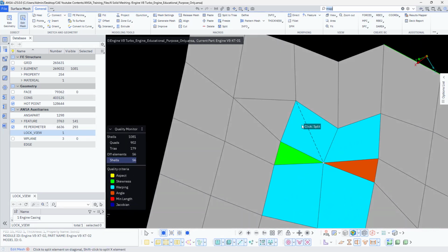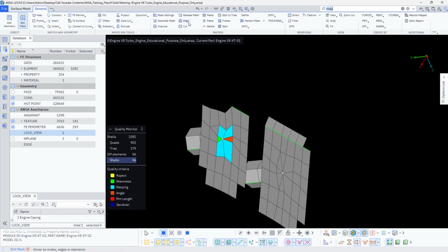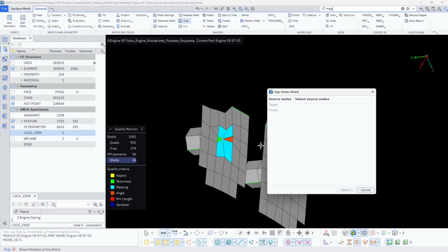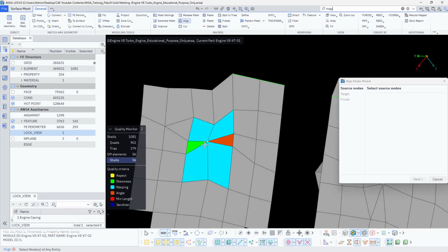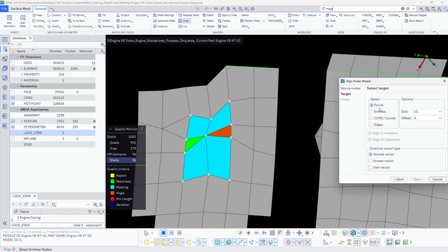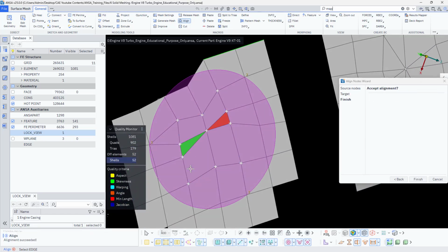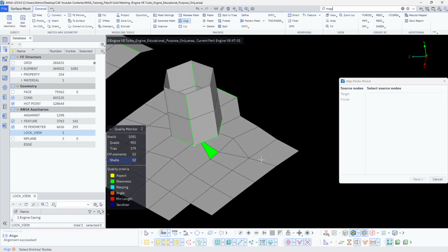Now you should align this with this surface. For that, you can go ahead with the align tool. So we have the shortcut also. Alt A is the align. So you can select the elements. So you can even select with the entities also like this. Okay. So these are the regions which I need to align. So middle click. So it will ask you for the normal to vector and points. So I'd like to define the regions. Like if you define 3 points, it will take the flat surface like this in a circular manner. I'll just middle click, and this is how it fixed.